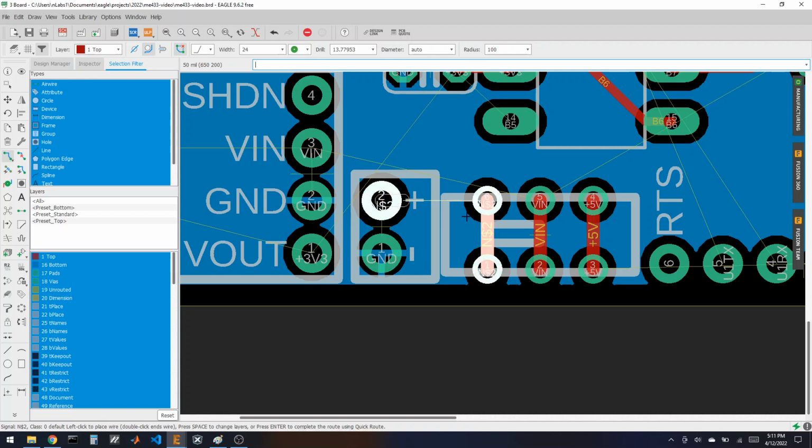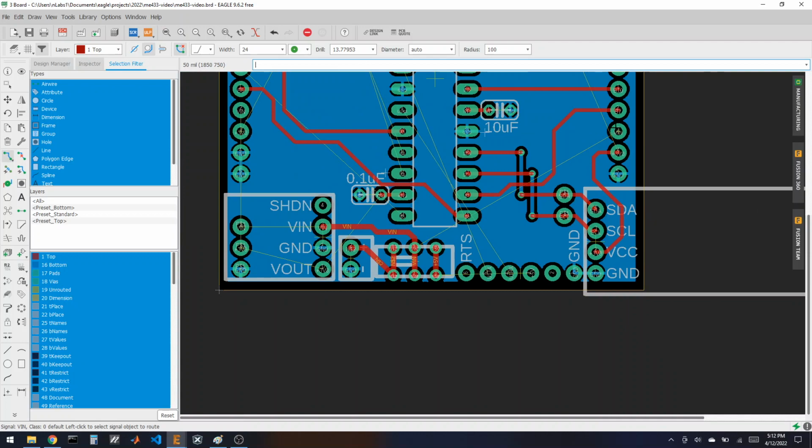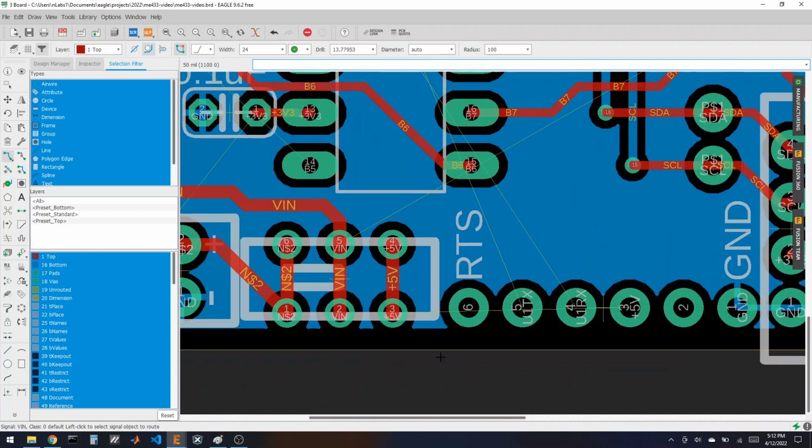So the battery connects to this part of the slide switch, and VN is able to power the regulator. Then we have to get 5 volts out of the USB to UART connection. Must be over here somewhere. And I wonder if this should go on the bottom, because later on we need to get those guys through here. But our top to bottom is blue, so probably should be red.